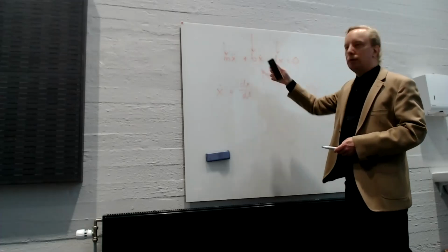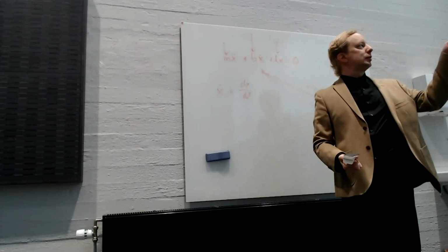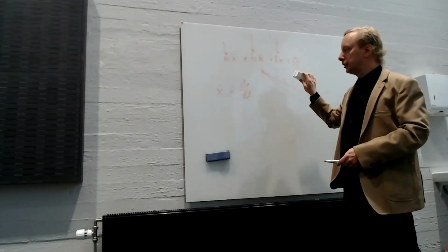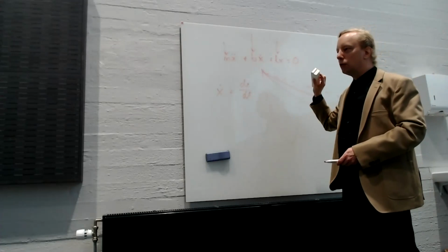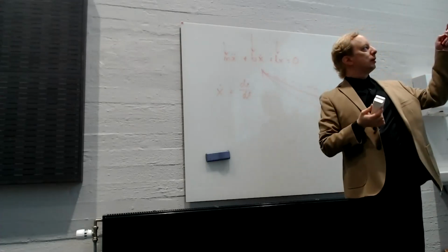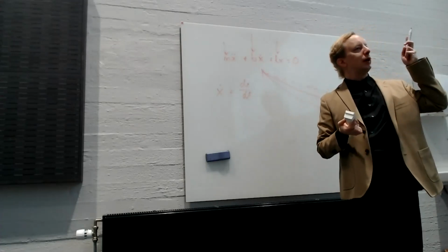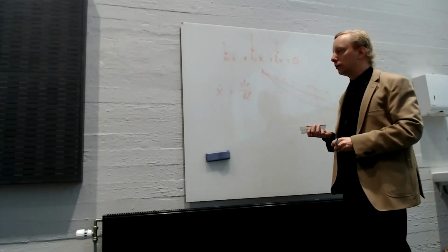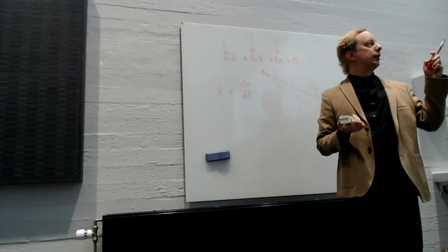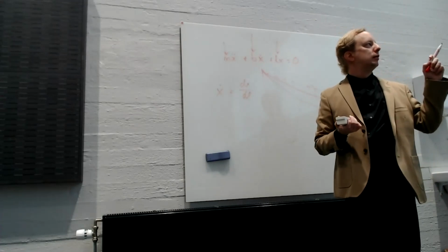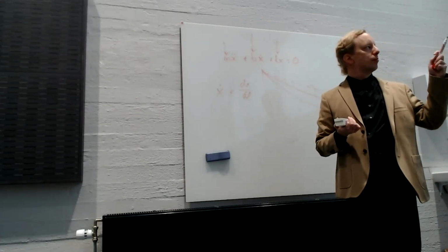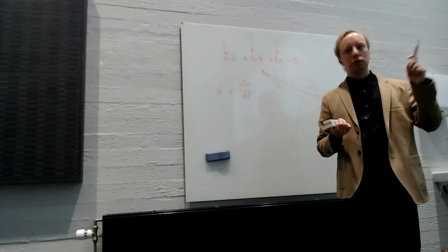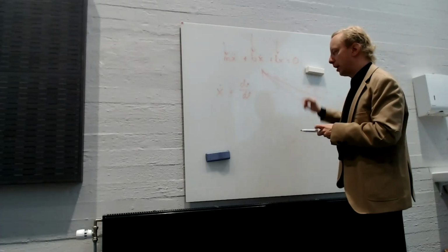You can probably do this experimentally. If you start increasing the factor b and see how the solution changes, you should be able to figure out which of the cases from the lecture material corresponds to critical damping, and then find a formula for the critical damping factor.